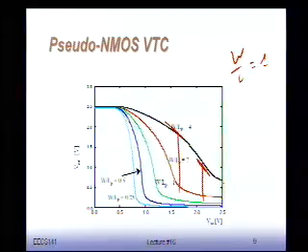Now, from the time I start making my PMOS smaller and smaller, your voltage transfer characteristic gets better. For instance, if I make it 1/4 of the NMOS size, you see I get a fairly nice characteristic. But actually, you also get a very nice one already if I make W over L equal to 1, the same size as the NMOS device. I still get some VOL, but it's not very large. And that's why we chose this all-transistors-same-size type of model. It gets you a decent voltage transfer characteristic.